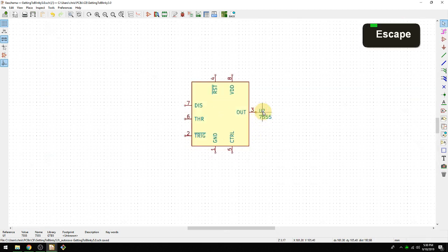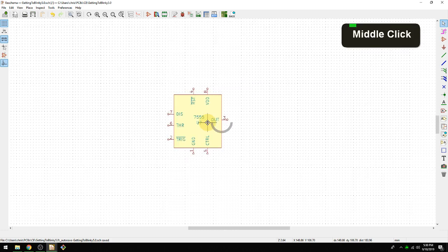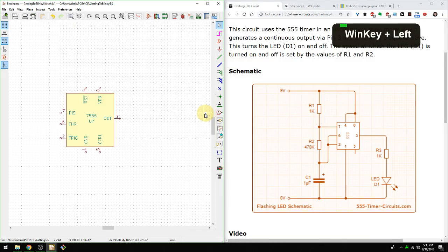You do see that sometimes these move outside of the component itself. Personally, I like to have them on top of the component. I think that's a little bit simpler. Again, that's going to come down to maybe what your company's doing or what you're used to doing. But we've basically now replicated at least the symbol in the middle here, and we're good to go. The question mark on the U will come up later when we annotate the schematic, and that'll give it a number, probably U1.